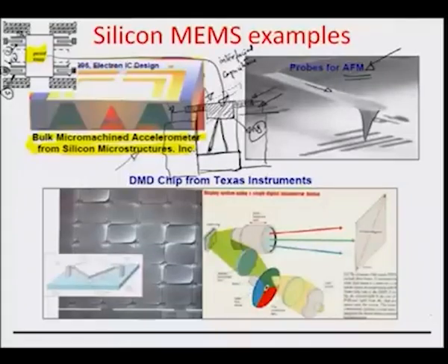and this again is used extensively for topological measurements of surfaces, where this cantilever tip is moved over a rough surface, and whatever crests and troughs are present on the surface are being monitored by monitoring the deflection in the z direction of this particular cantilever.